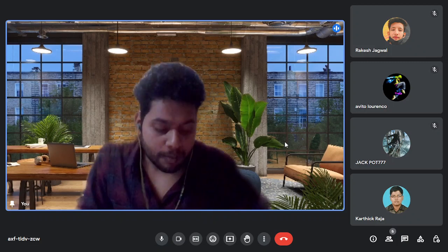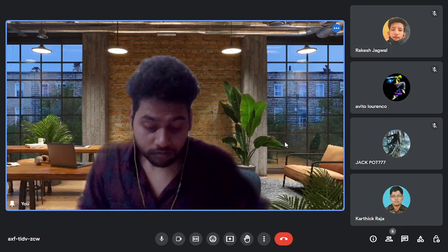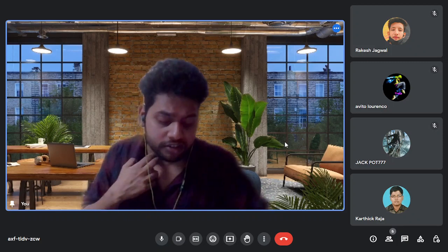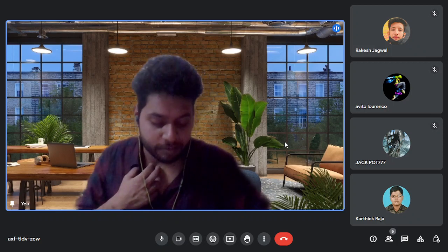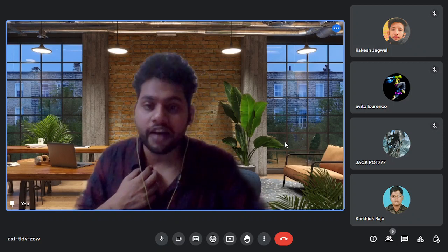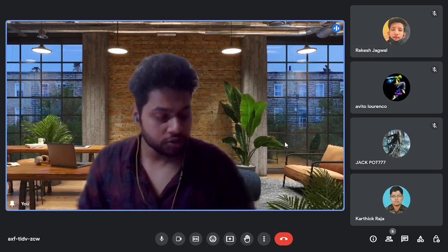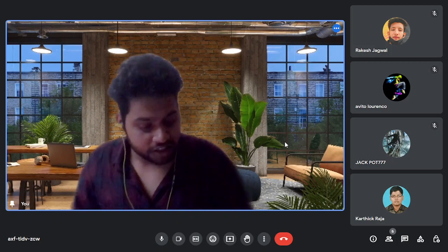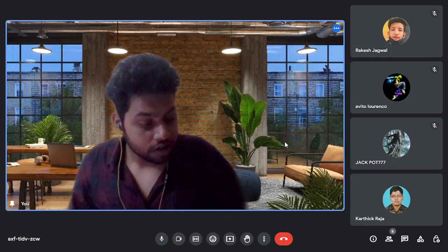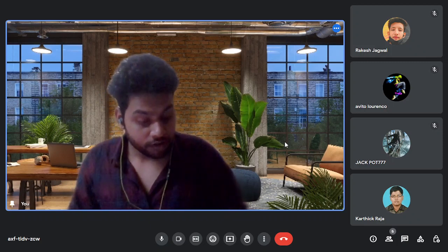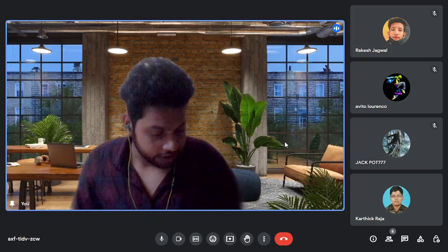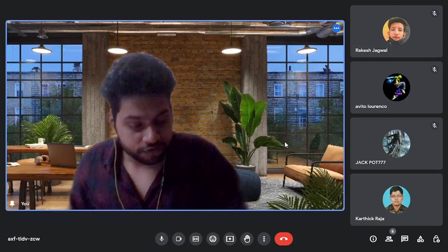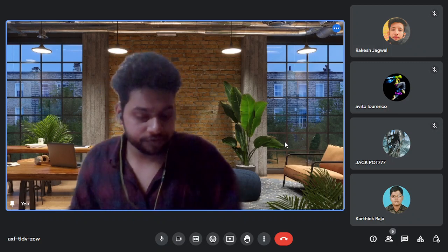A capacitor is a passive electrical component that stores energy in an electric field and is characterized by its capacitance, which is measured in farads. Now the cross question was, which leads? In an inductor its voltage leads, and in a capacitor its current leads. In a resistor the phase difference is 0.